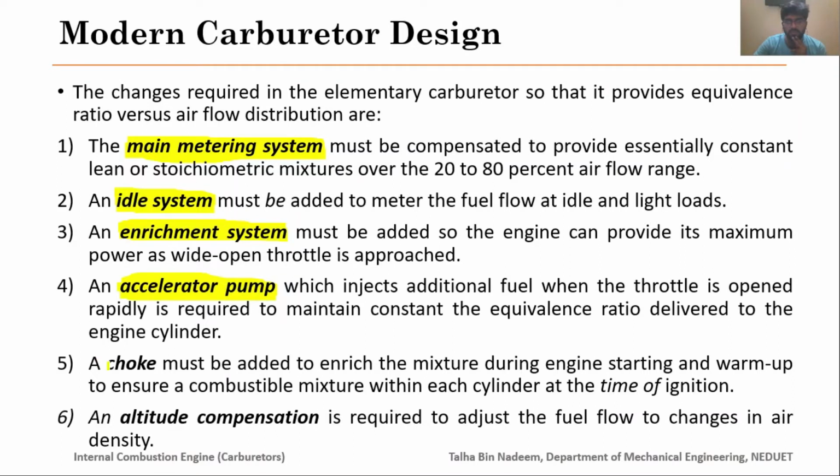Next is the choke valve. Sometimes you require a rich air fuel mixture and your engine is not starting, therefore you rotate your choke system and then the amount of air going into your system is adjusted, and ultimately it will combust the fuel, and then your bike or engine will start. Choke is quite helpful in starting a motorbike.